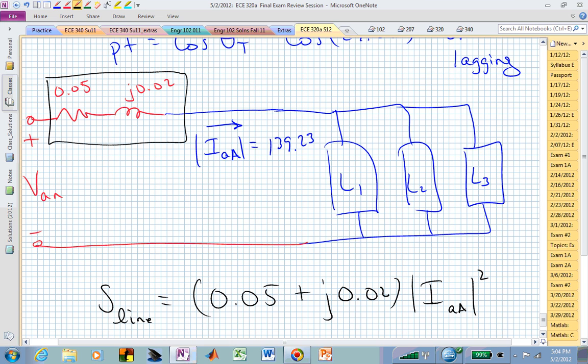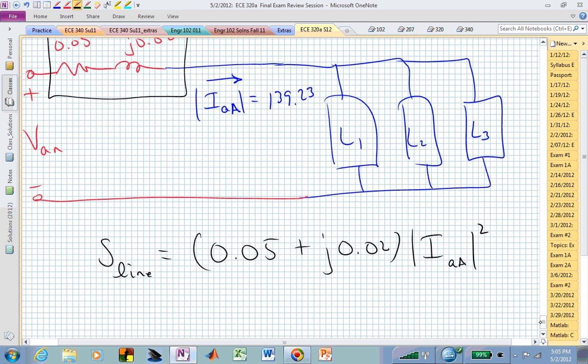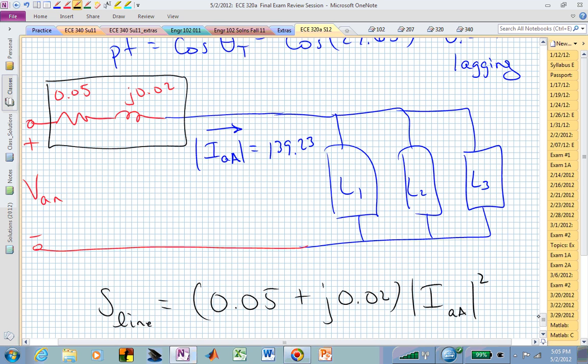And that will now give you a complex value. I'm sorry, I'm mixing a lot of different things. If I just needed V sub AN, I just need this voltage drop, don't I? And now I could find that by looking at ZI. But what I might want to do is decide which of these values needs to be my reference phasor in order to keep track, because you can't just add magnitudes of voltages. You have to add these vectorially, and you have to keep track of the angles. Questions on that?